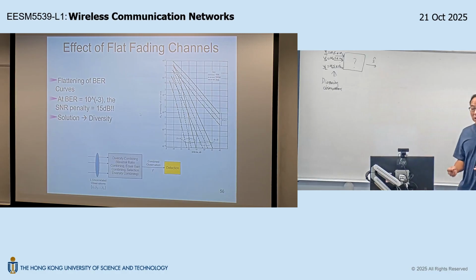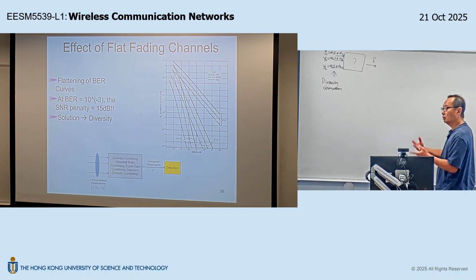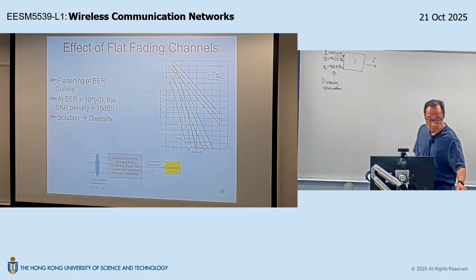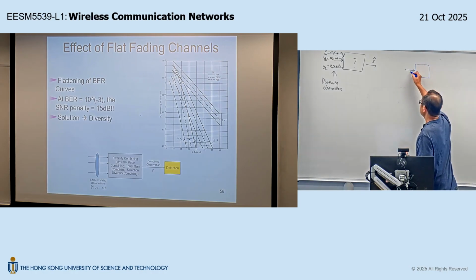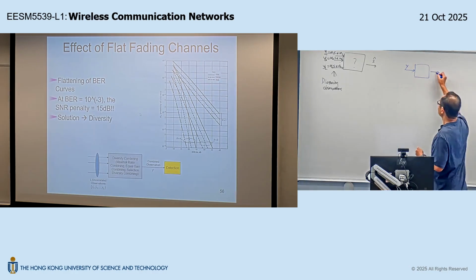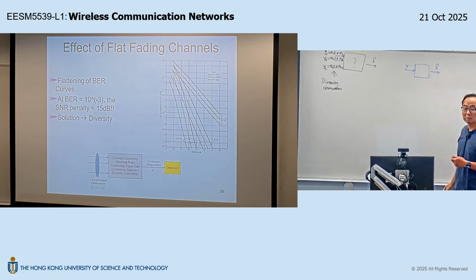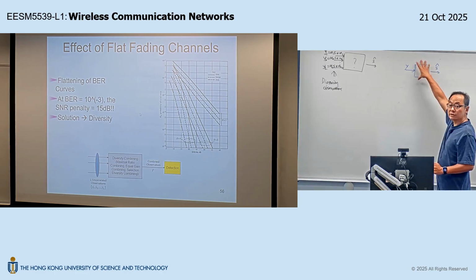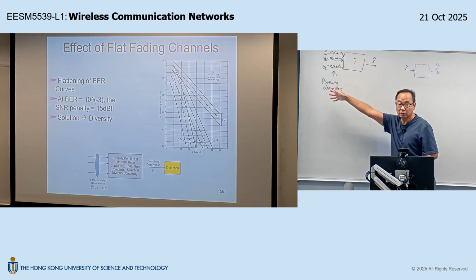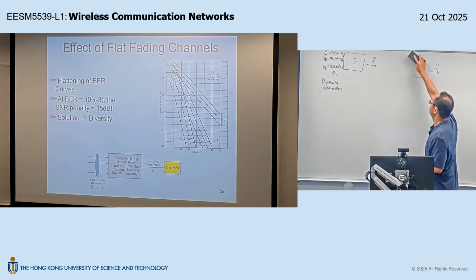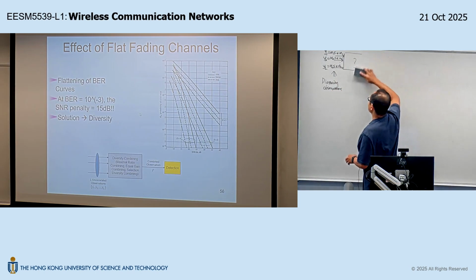Previously, when we talked about digital modulation, we said that the demodulator should do something called minimum distance demodulation, right? The input is one observation, the output is the detected symbol, and here you apply minimum distance. So with this minimum distance demodulation, how do you interface with multiple observations at the input? The proposed architecture will be something like this.